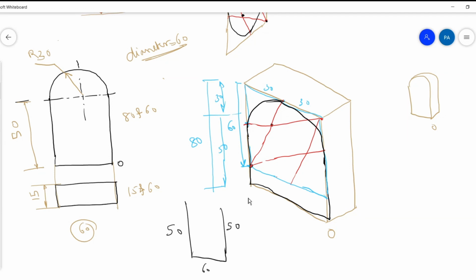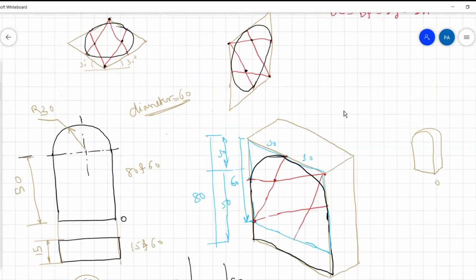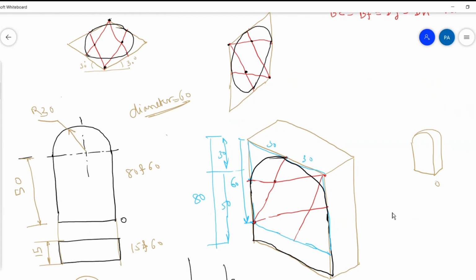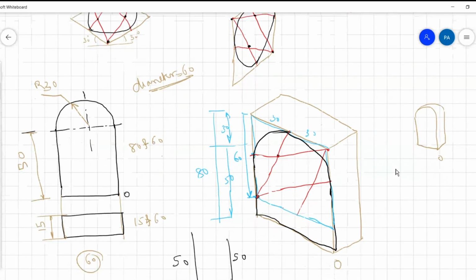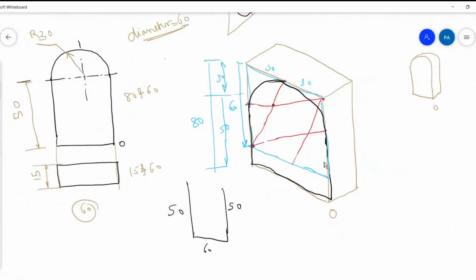you complete the rhombus. Once you complete the rhombus, you know the procedure. After you complete the rhombus, this is the procedure. Then we have followed the same procedure, and we have constructed these two. Now, how many parts do we construct the ellipse in? Four parts. Yeah, so instead, now this is a semicircle.